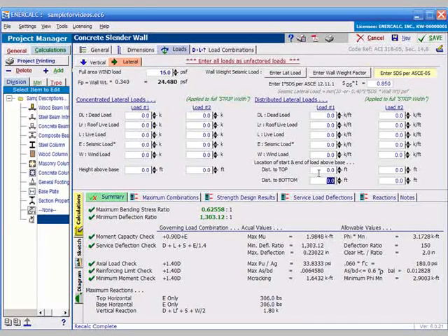either apply that lateral load as a partial length lateral load on the jam at a distance starting at the top of your opening up to the top of the wall, or you could assume that the weight of wall panel above the opening spans vertically between the roof ledger and perhaps a bond beam that you've constructed in the thickness of the wall panel, and then that bond beam would carry the load out to the jam where it would apply it as a concentrated load. Of course, these are rigid, stiff panels, and the load paths are theoretical anyway, unless you want to do a finite element analysis. But these are the most common ways that engineers do the approximations of those loads.